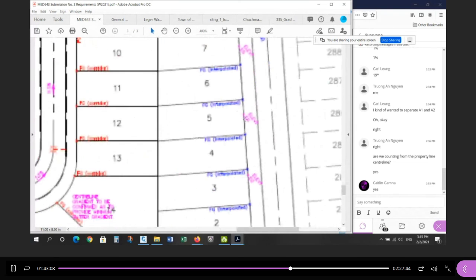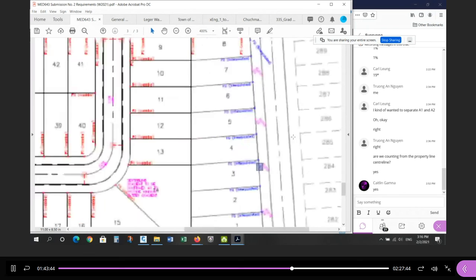The ones here you can also interpolate. So between here and here, you can interpolate these 2 values. Or you can get these 2 from the corridor model we just created for Ledger Way. And I would do both just to compare, right? If you interpolate between here and here, you're going to get values for these 2 positions. And then you can get these elevations from the corridor model. They should be, if not exactly the same, very, very close. Okay, so there's a couple of options here. I would prefer you use the corridor, but it's not wrong to interpolate between the points, right? You might get a slightly different result, but they should be very close.